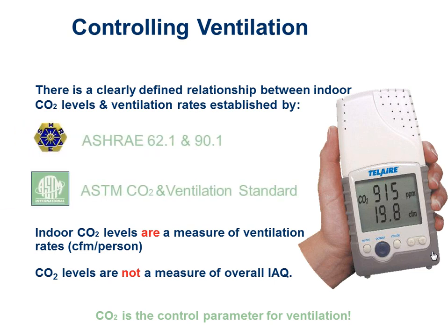All right, the first thing we're going to look at is some of the standards involved in here. ASHRAE 62.1 is our national ventilation standard, if you will. The International Mechanical Code is our national code, but all the data for that pretty much comes out of ASHRAE 62. It's the backbone of how we ventilate commercial buildings. ASHRAE 62.2 would be how we would do it residentially. Additionally, there are the energy standards and energy codes that come into play. And ASHRAE standard 90.1 is our model energy standard for the entire country. And the International Energy Conservation Code, which most municipalities and states adopt, does follow the same language as the 90.1. So pretty much everything begins with ASHRAE.